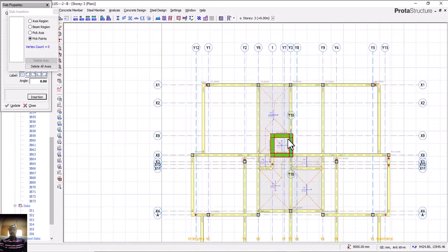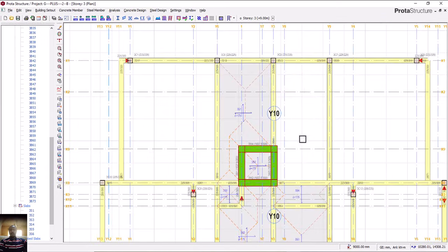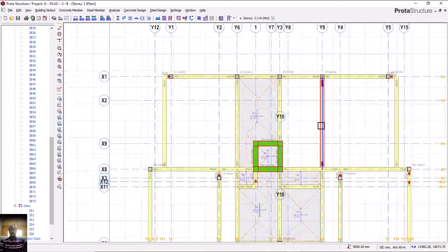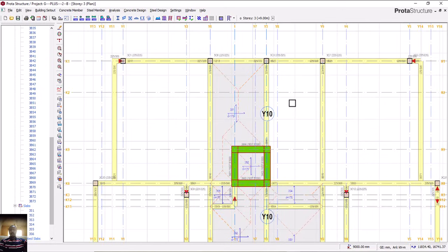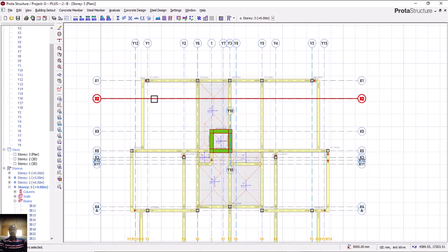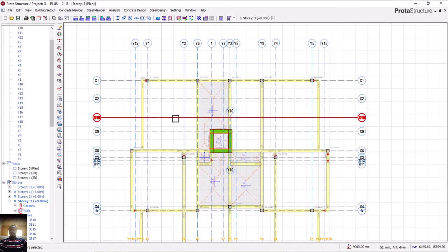It's still not working. Looking at this place now, since it is long, I can decide to put a beam to break this span here because it seems to be too long. Let's check the length. Come to this place, 5 point something. So I'll take this one from here, offset it, and put it at the middle, using your eye gauge. This one does not really need something, so click on this one now, right click.